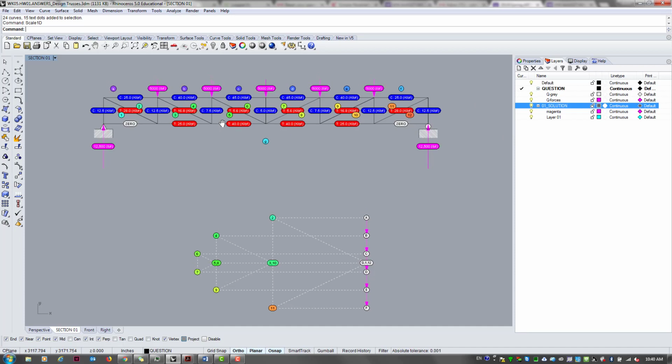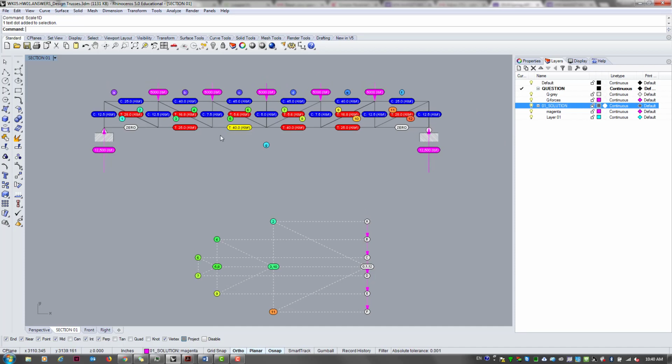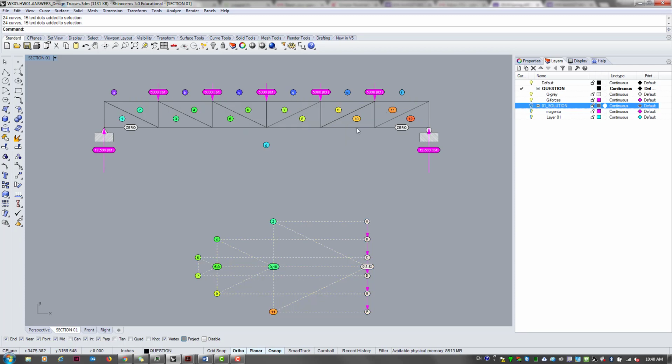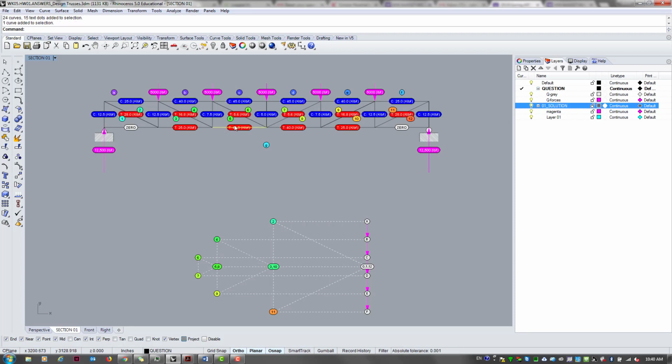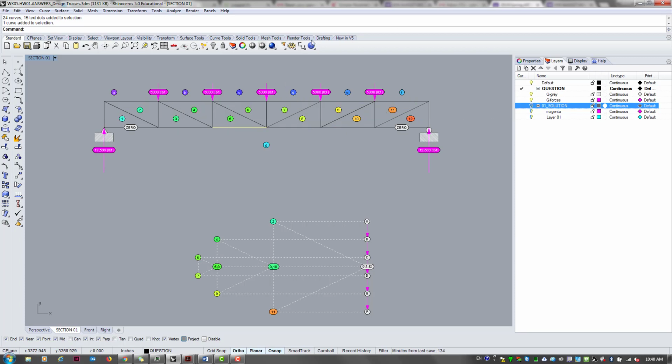So now what I was asking you is to reduce this tension to 16K. Because none of the other conditions are changing, we can pretty much directly manipulate the diagram first and then use that as a guide to determine the depth of this truss. So let me turn off this layer because I don't need it. But just to remember, 5G, that member was 40K, because if you do a dimension, let me use a different color.